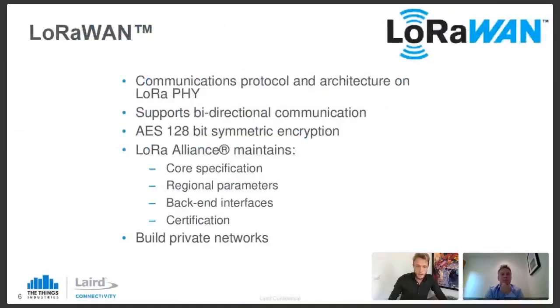So LoRaWAN is typically transmitted over LoRa modulation. It's an open protocol. It's two-way communication. It contains session management, security, network layer, and application layer encryption. And it's governed by the LoRa Alliance. The LoRa Alliance has a technical committee where the specification is maintained and expanded. There is also a specification on the regional parameters. So those are basically the rules